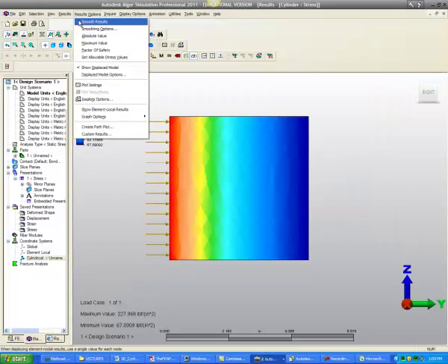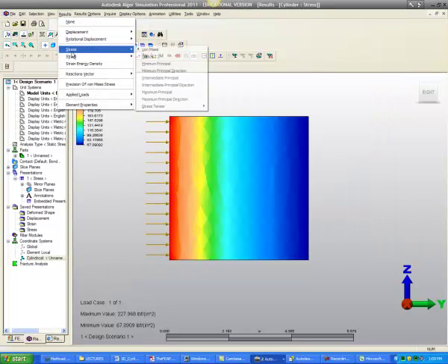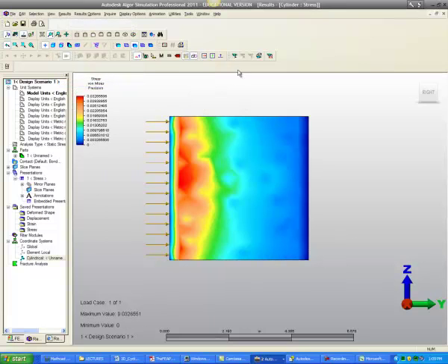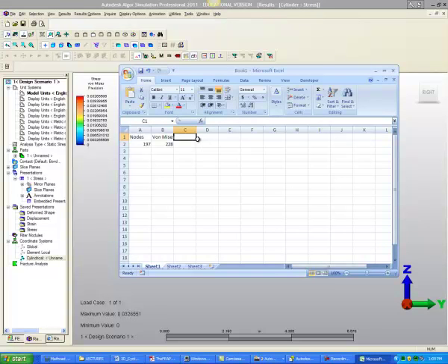Now let's look at our precision, results, stress, precision of von Mises stress. Oh, I don't even need to remesh this, guys. In fact, I'm not even going to bother setting up the spreadsheet, I don't think, because we're going from 0 is minimum, maximum is 0.03 on a scale of 0 to 0.5. That's really, really good. I really don't think we need to remesh, but we could just to see what happens. Let me enter the precision here of 0.033.